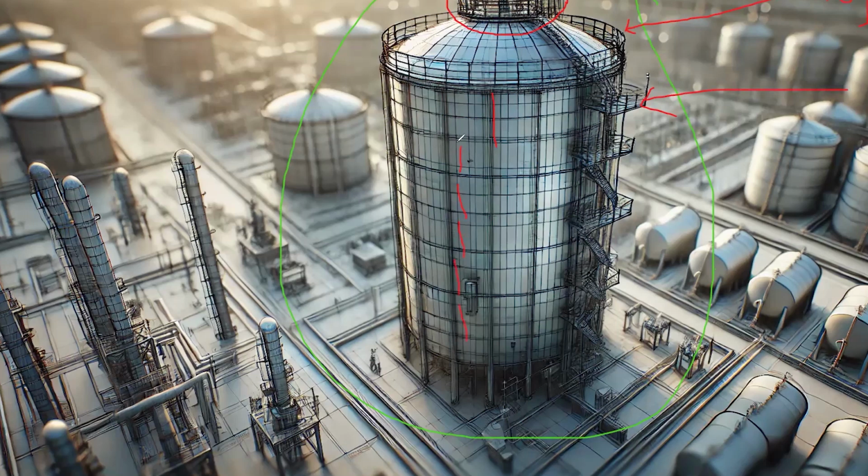So there are 1, 2, 3, 4, 5, 6 shell plate courses. They will be fabricated separately, right? Their rounds are going to be considered one by one. So this portion is called the shell area of the tank, shell. And then this area would be considered as the bottom plates or sump, bottom and sump. Sump relates to that certain valve which is going to take all the drainage and all that, the outlet valve you can say. So this is the bottom plate area.